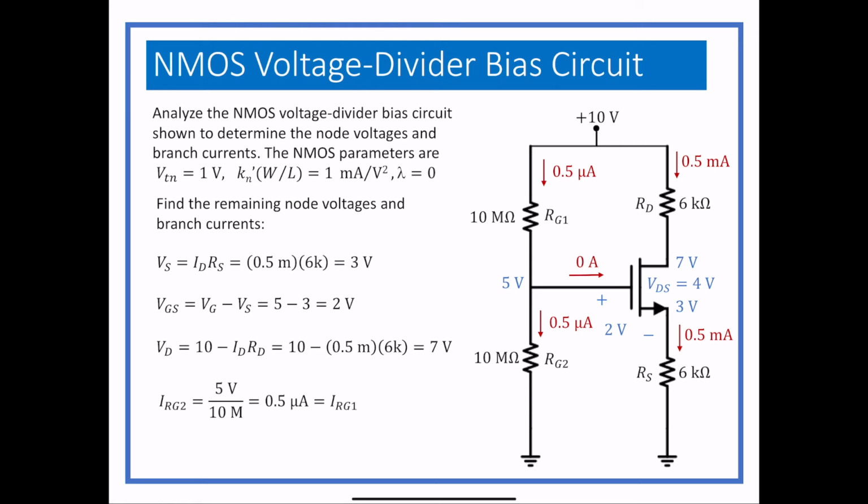Another conceptual question. Yes. So when you're actually using an NMOS bias circuit in whatever you're prototyping, would there be a load connected to RG2 and RS? Where would the load be connected? The load would be right here. That would be RL, and then your input would be right here. So this would be in, and this would be out.